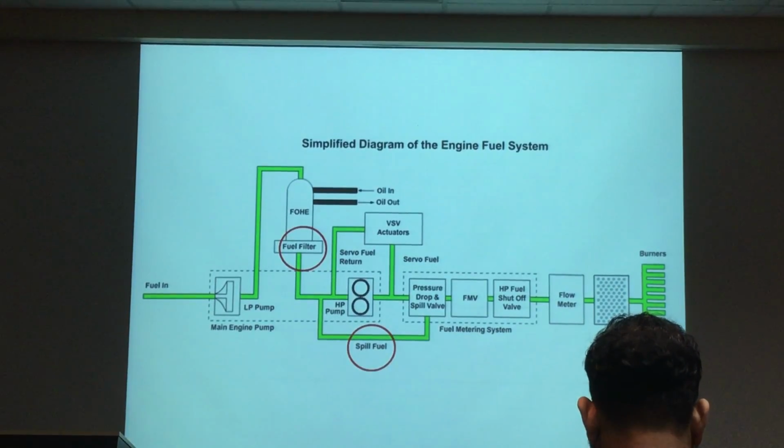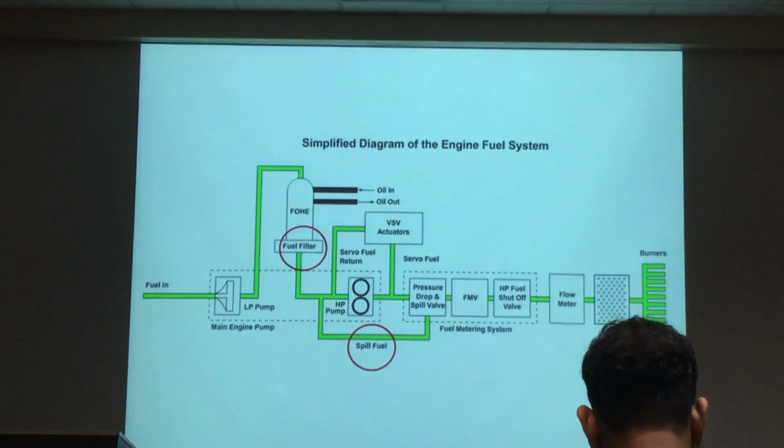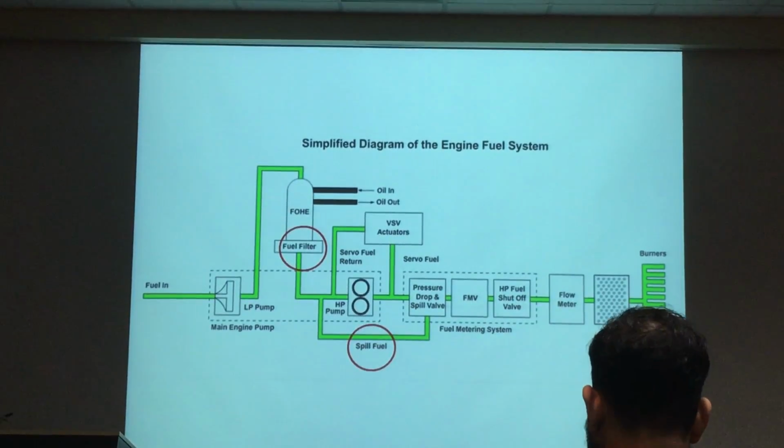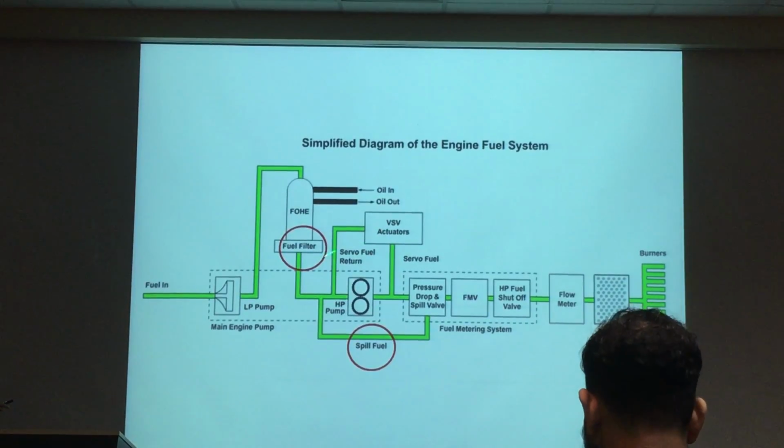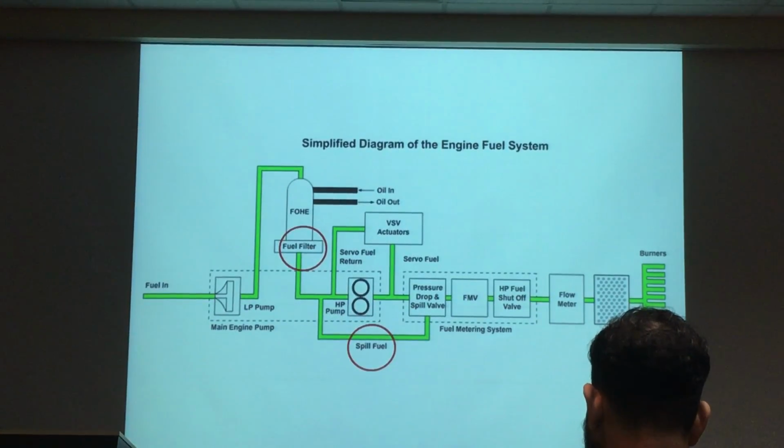Okay? Your engine fuel hydraulic comes from here, the HP pump. Remember, your FCU computes your metered fuel at the same time. It also commands all the hydraulic actuators, all your controls. All controlled by your FCU. Remember FCU? Finally, you do two things. One is meter fuel. Secondary is this one. All your actuators are controlled by fuel hydraulic.